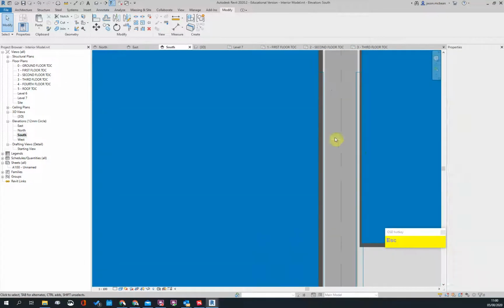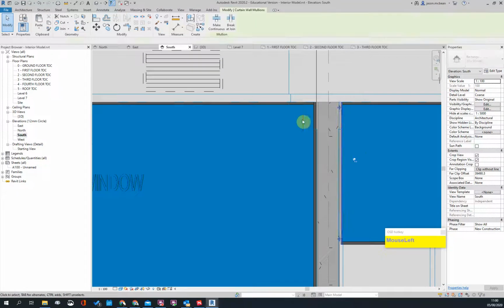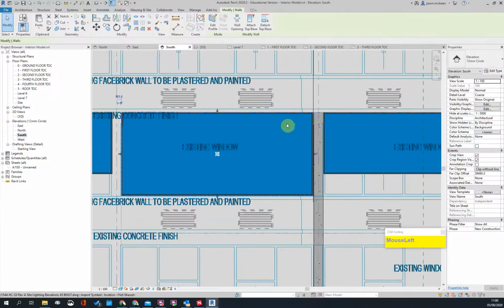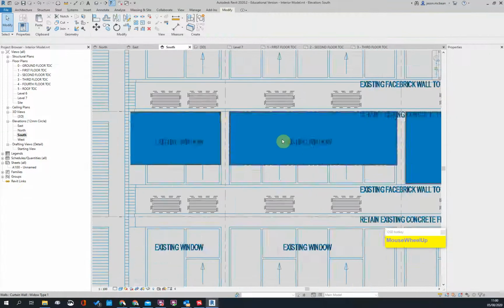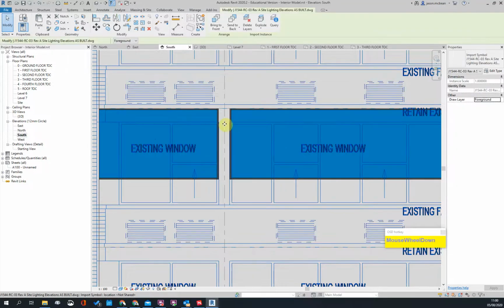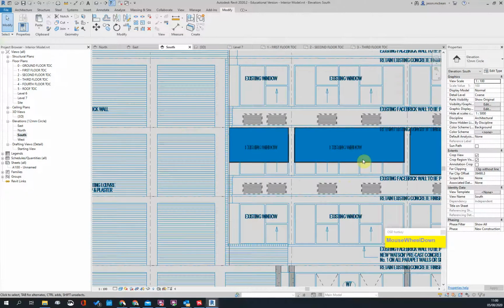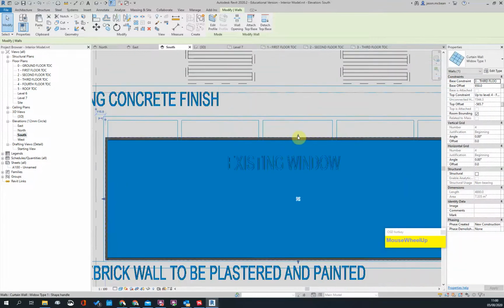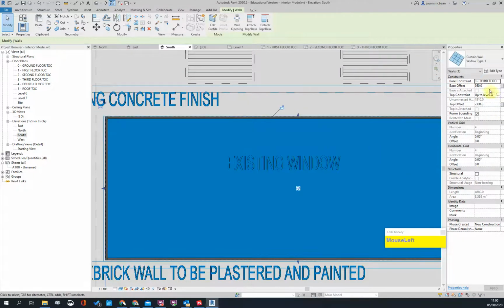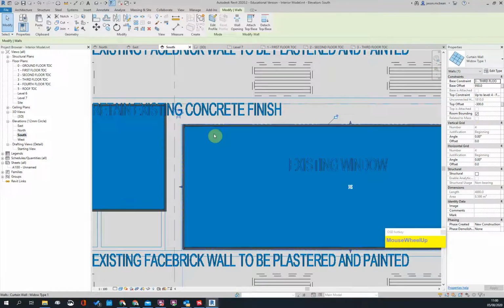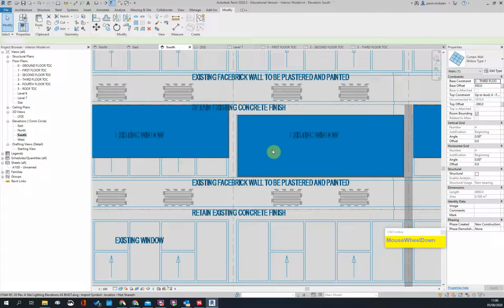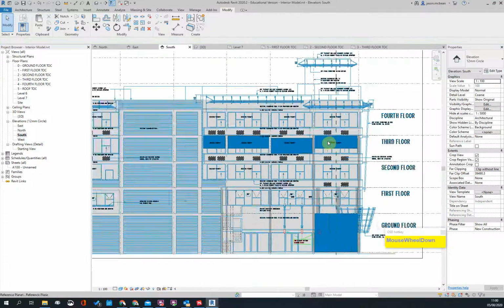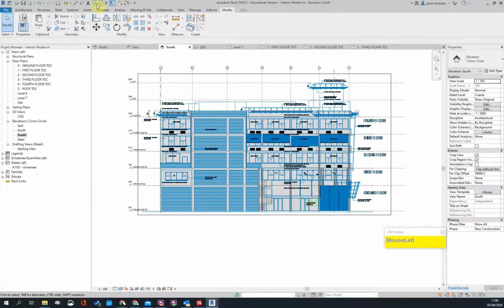Likewise with this. And you can see these do go to the top. These windows go right to the top. So let's pull this. Oh no, they don't. Okay, so I'm just going to fix one and I'm going to match the properties with all the rest of them. So this will go to the top. So let's see, it offsets by 300. So it's left a 300 gap and we've offset from the ground 9. Okay, so that's great. So in 3D view,